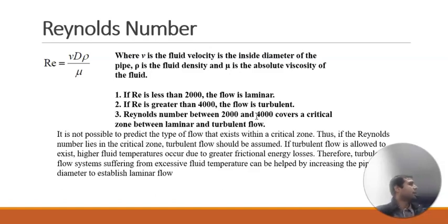If we change the type of the pipe we will have a lesser friction coefficient, and that will help us to change the value of the Reynolds number. Sometimes, because viscosity is directly linked to temperature, we can increase the temperature of the fluid before pumping it from A to B. Hence, it will reduce the turbulence. But while you're doing it, you are utilizing excess energy.